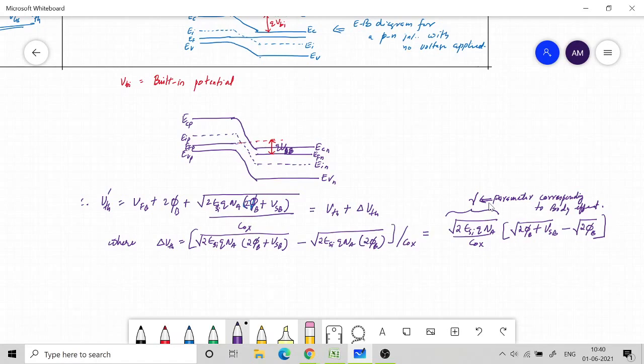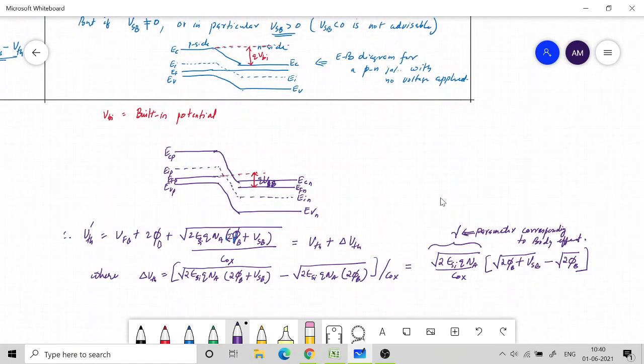So it is more like an empirical parameter, you can't really derive an accurate value of gamma. But here I have shown it in such a way just to give you an idea what is happening when you apply a negative potential at the bulk compared to the source.